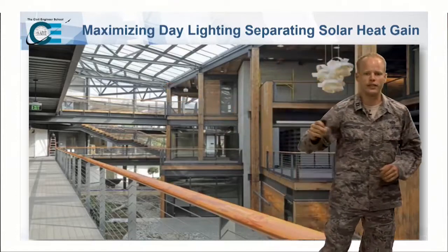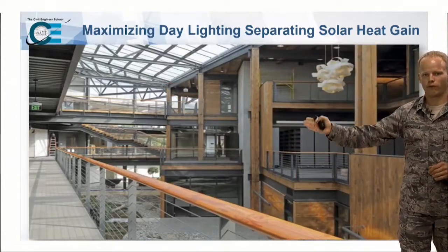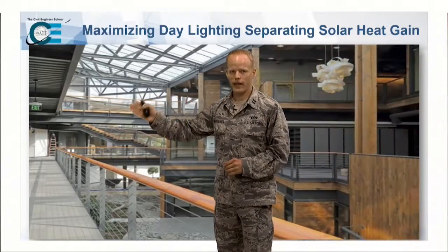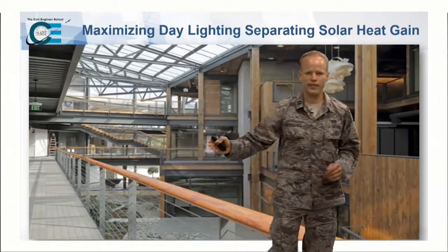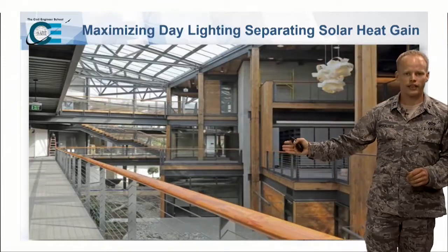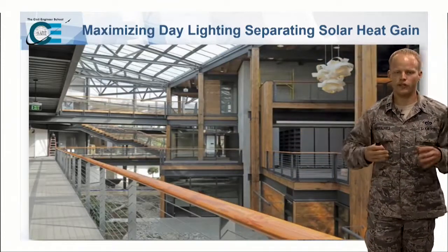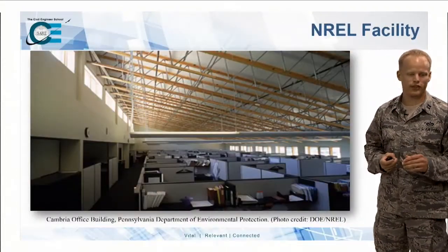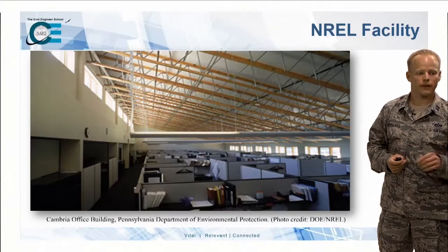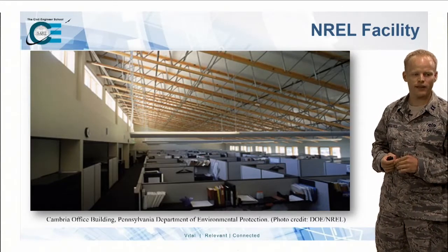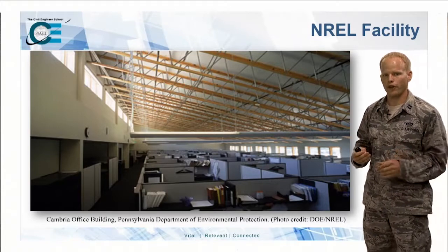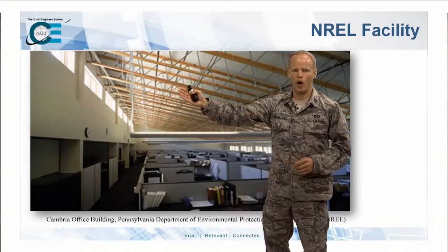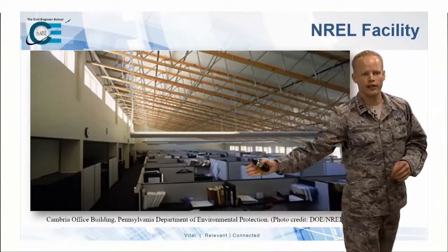We have over here lots of daylighting. Then you look at each of these rooms, they are segregated from the rest of that main hallway. So this hallway, you don't have to heat or cool as much, but this side now are your conditioned spaces. You separate these loads and you can save energy that way. This is the NREL facility. This is actually from Pennsylvania, but this looks exactly like where I sat, where they're allowing daylighting to come in from these windows. They hit the wall, which reflects down and onto all the occupants.